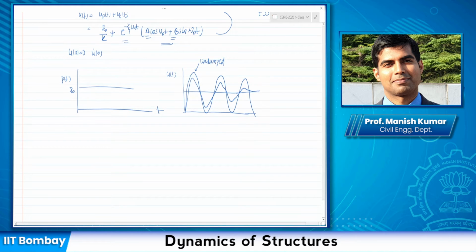For this type of situation, the loading is represented as a step loading. If you jump on a platform, it is a step loading because you have load mg that you apply suddenly and then maintain. The same is the case for a digital scale. In those cases, if you want the system not to vibrate too much, you can increase the damping so much that the system comes to rest very quickly.